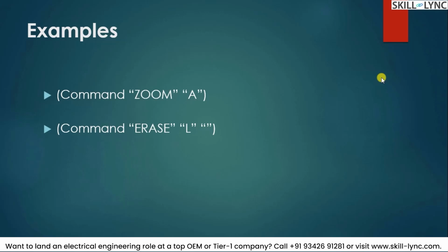So that is why it is followed by the double quotes command. Likewise, for executing a circle with radius 1, you can see the command, space, circle within double quotes, space, pause. So now, once this circle command is executed, AutoLISP waits for the user to give the input of the center point. So it is pause for that input. Once the user input is obtained, then it will go for the next sequence.